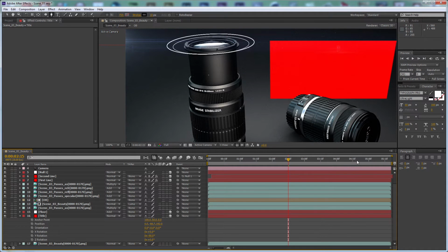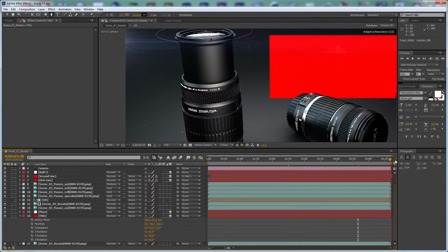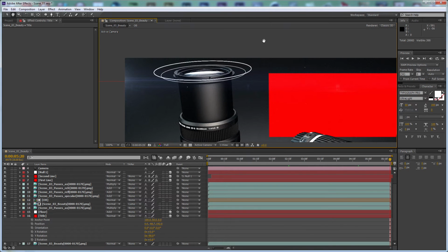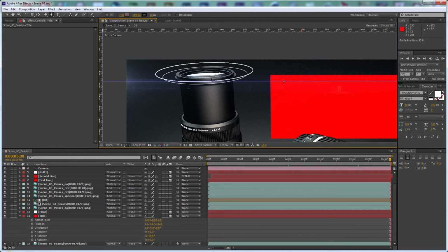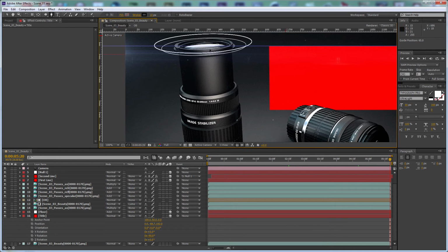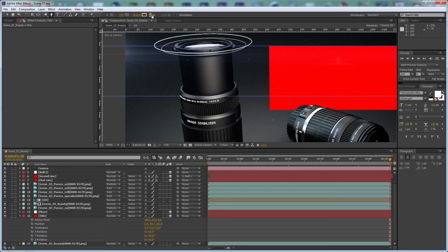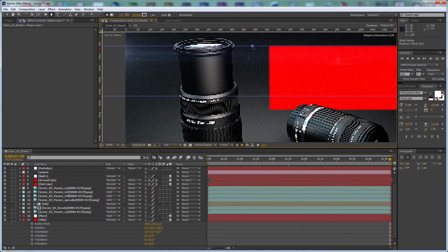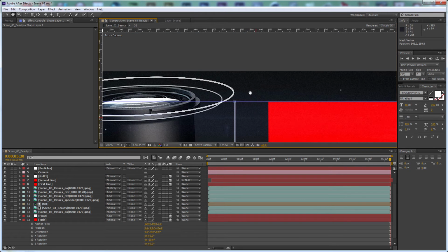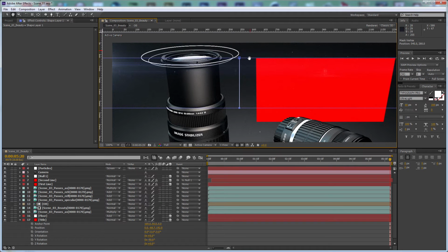So at this frame, we are going to create two marks here. Let's see, one here and one guide layer here, and I'm going to just make sure that nothing is selected and change the color to white for the stroke. Set this to 2 pixels and click here and hold down Shift and click here and just drag the point, and that's it. That's our animation so far.